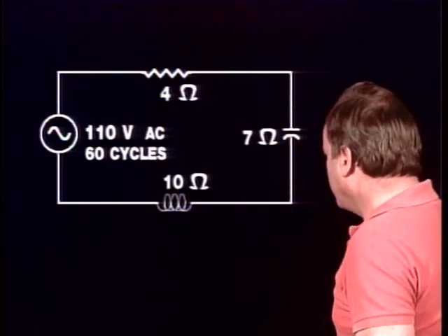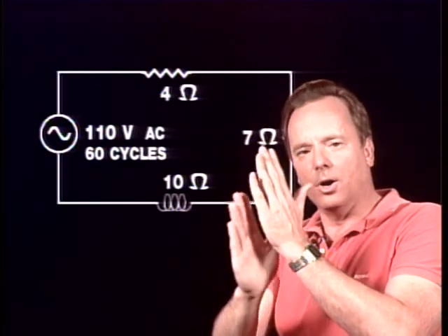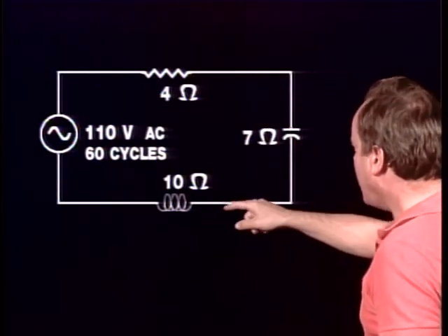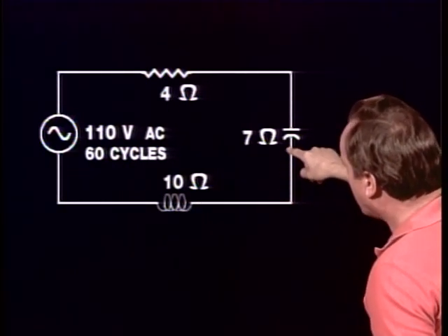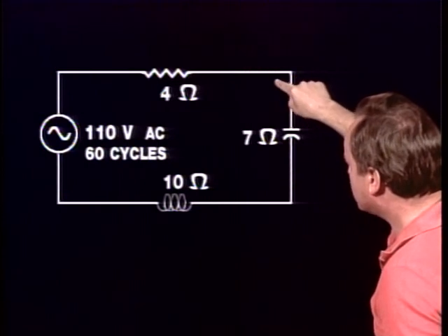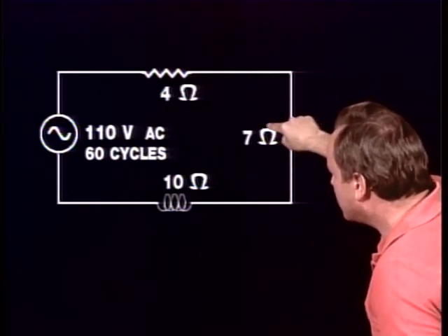Now, there's another thing installed in this current we haven't talked about here. We'll talk about that, and that is capacitance. Now, capacitance is basically two metal plates next to each other with an insulator, or a dielectric it's called, in between them. And what happens is, remember, this is current that tends to build up a charge, and as the current flows, it charges one of these plates. So let's have the current coming through here, charging this plate.